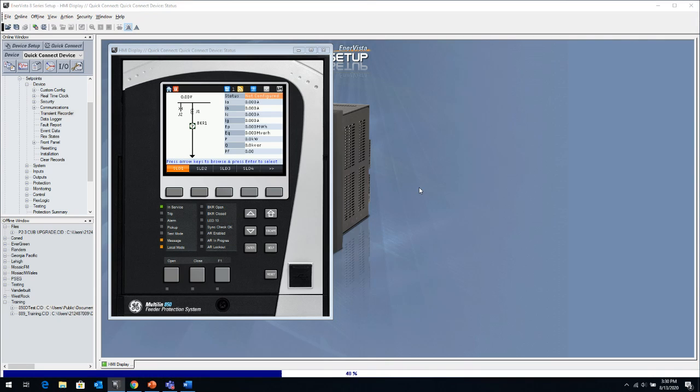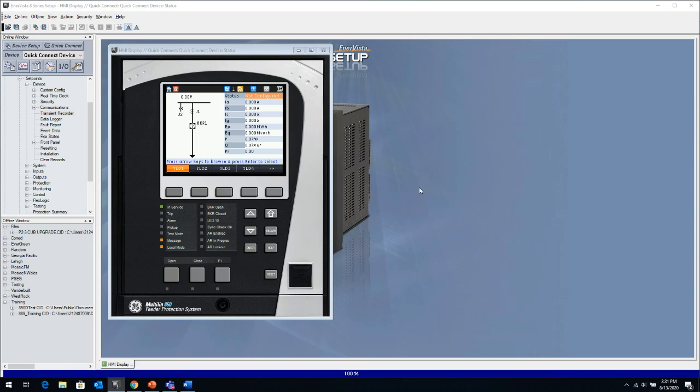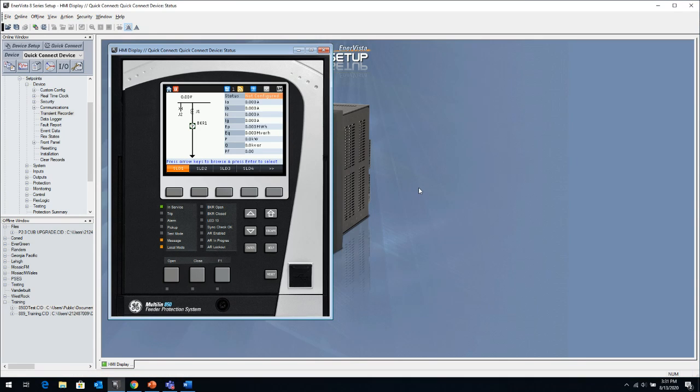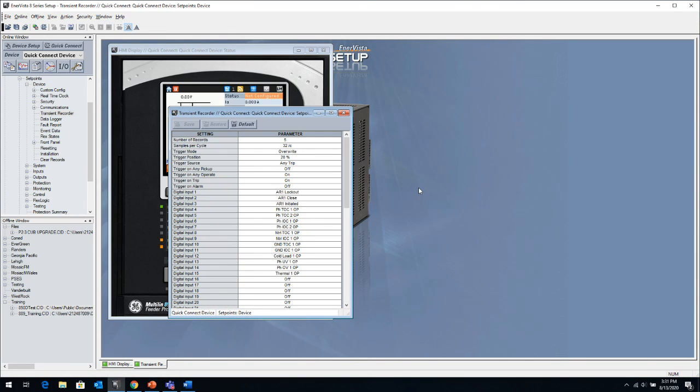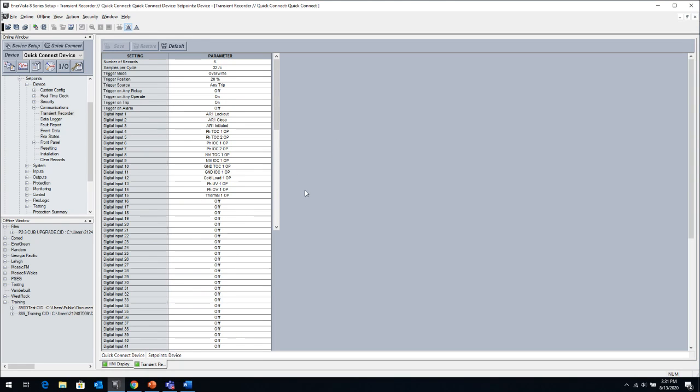Why is it important to have a good oscillography setup? Because if there is an event, whether a relay tripped properly or didn't trip properly, or misoperated or didn't operate properly, once your event is triggered, the event report gives you a snapshot of the power system when that disturbance occurred. So you get the analog waveforms, all the data the relay is reading, all the trip signals the relay is experiencing in that oscillography, where you can line it up. So it's important to set this up.